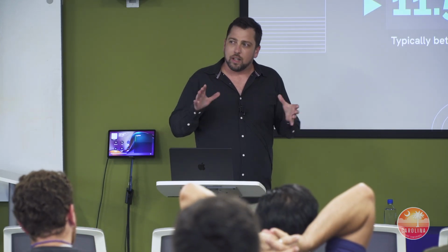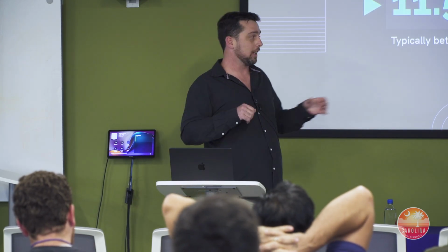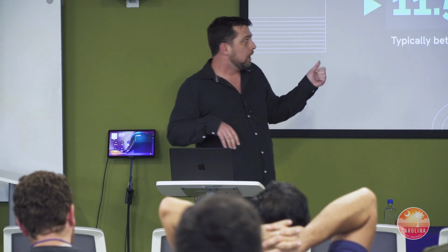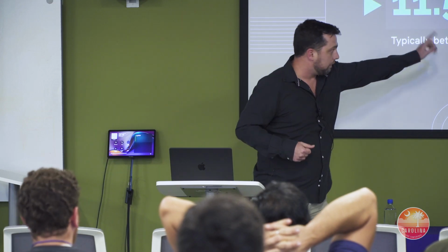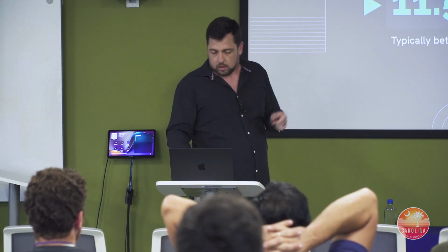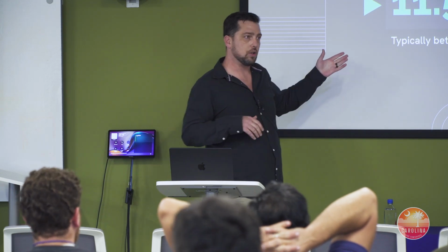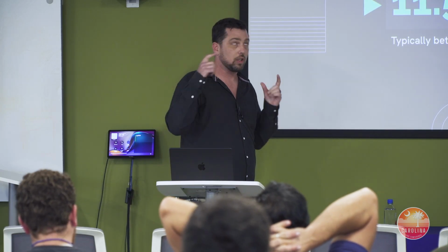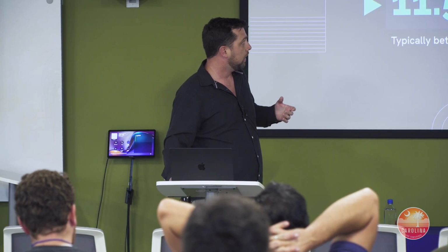In the electrical engineering industry, which I'm not classically an electrical engineer, but you learn things as you go, the rule is you should never exceed 80% of a breaker, and standard breakers are 60 or 100 amps, and so chargers are manufactured at 48 and 80 amps. So again, it might take you overnight to charge your vehicle. These are the most prolific chargers. These are your Tesla chargers. If you're around downtown Greenville, they have a bunch of Clipper Creek chargers in the different parking lots. That's what that is, an AC charger.